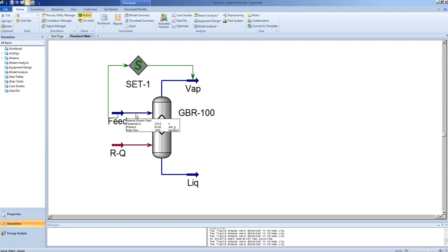So, in summary, when the reactions that are taking place are unknown, but we are investigating the behavior of the reactions as they approach equilibrium, or the system as it would approach equilibrium under the given temperature and pressure, we would be able to use a Gibbs reactor to do this. The Gibbs reactor will predict what reactions take place and will carry those reactions to equilibrium.